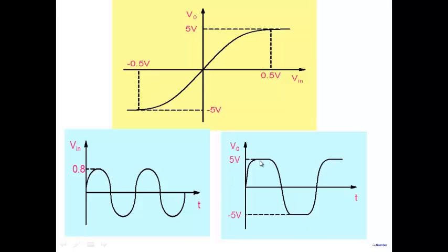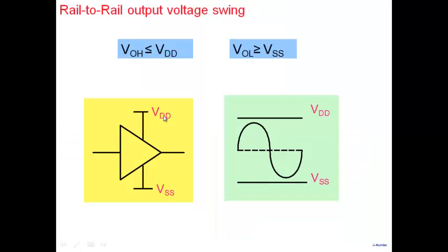So obviously when I get clipping here and I get clipping here, output is distorted and that will show up as a harmonic distortion. I will get second harmonic, third harmonic, fourth harmonic and all that. So I don't have a pure sinusoid, I'll have a harmonic distortion here. That's coming about because of limitations here, that there's a limit on how large the output voltage can be and how small the output voltage can be. Okay, so the saturation here and saturation here.